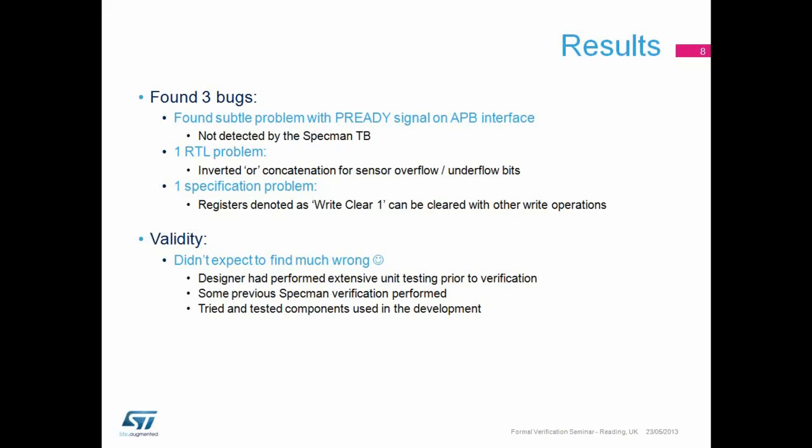One RTL problem, so there was an inverted OR concatenation, a typo in the RTL, and a spec problem as well. So it actually highlighted an issue where a lot of these registers we pinned down as being write clear 1, so you could only clear them by writing 1. We found out actually you could clear them by writing anything to them.